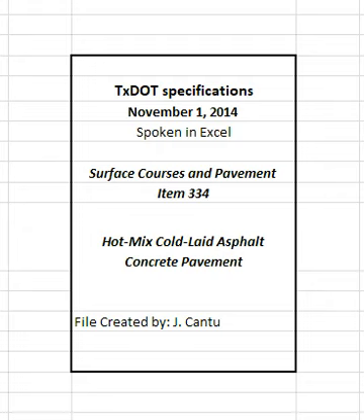Use only water or an approved release agent on rollers, tamps, and other compaction equipment unless otherwise directed. Keep diesel, gasoline, oil, grease, and other foreign matter off the mixture. Use tamps to thoroughly compact the edges of the pavement along curbs, headers, and similar structures and in locations that will not allow thorough compaction with the rollers.